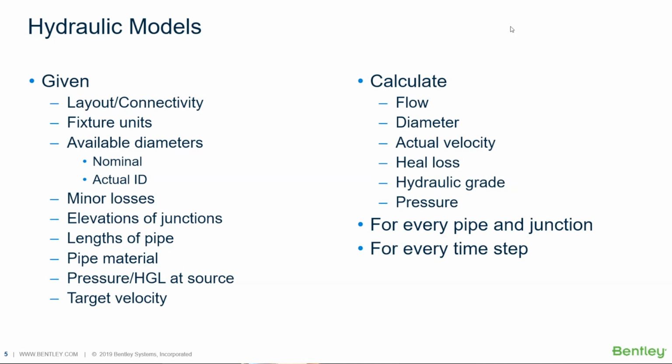But most of that stuff you already have at your fingertips. And what you get out of this is what the flow is in every element, what the diameter is, what the actual velocity is, what the head loss, hydraulic grade, pressure. And we can do this for every pipe and junction and every time step. So it gives you the ability to simulate what's going on and create a digital twin of your system.